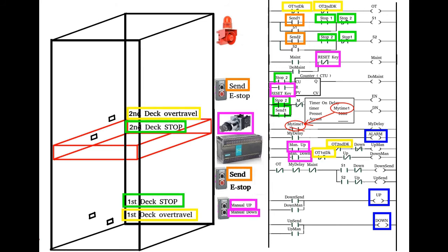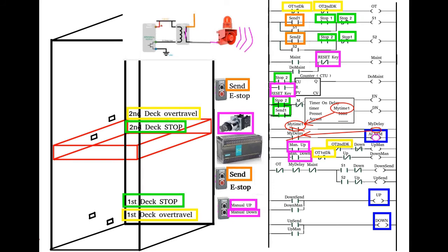This will cause my delay relay to energize, and it will close its associated normally open contact, effectively energizing the alarm relay, which is mapped to the output module, and it will sound for 5 seconds, because after 5 seconds the time delay will expire, restoring again or opening my timer contact and therefore opening my delay contact, de-energizing the coil for the alarm.